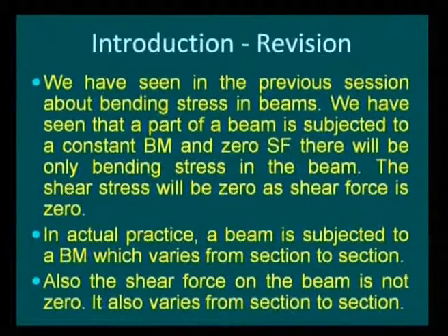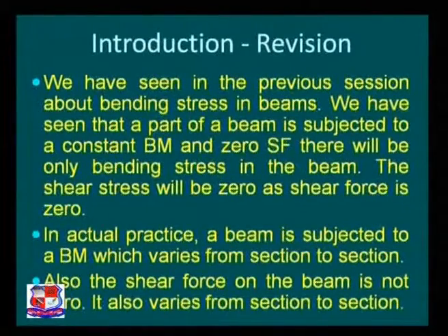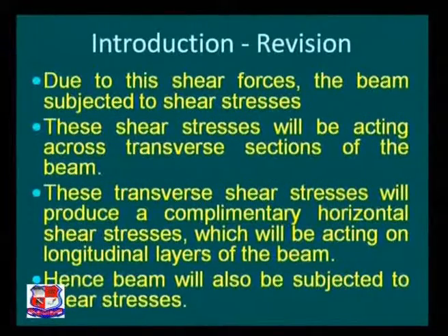In actual practice, a beam is subjected to a bending moment which changes from section to section. Also, the shear force on the beam is not zero. The interesting point is that the shear force varies from section to section. Hence, because of these shear forces, the beam is subjected to shear stresses, and right now we have to study the variation of shear stresses along the length of a beam, along a particular section.